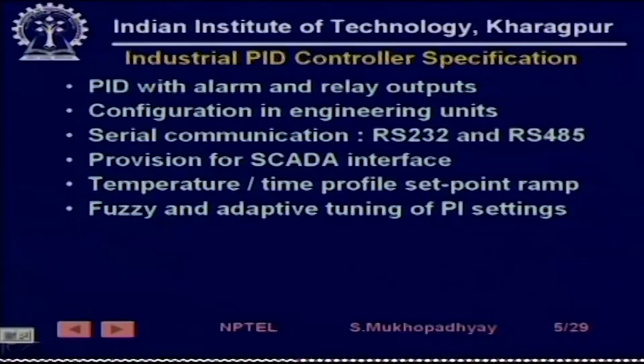Incidentally, the heat transfer coefficient tends to change because in the pipes you get depositions from seawater. So, in such cases, for efficient response as well as for things like energy efficiency, you need to tune PID controllers from time to time, and so they have provided algorithms for doing that using fuzzy means, there is a special technique called fuzzy set theory, which is used to design controllers.